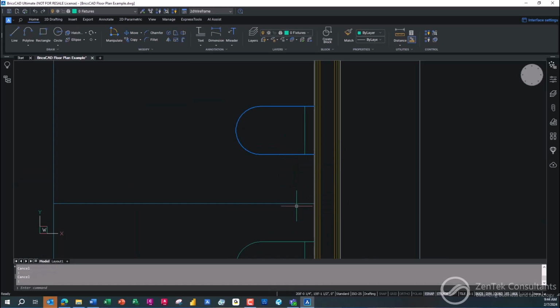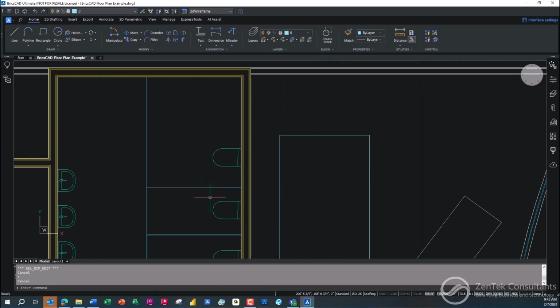I'll just click on the control, then here. Okay, that's 1 foot 1.5. Maybe that's not enough clearance. Now the key with this, the one that you pick on first, I'm going to pick the wall first, then I'm going to hold down the control and pick here. The one that you pick first will stay where it is. So instead of 1 foot 1.5, that's actually supposed to be 1 foot 4, 16 inches. All right, I'll just put in 16 inches, and you see, it moves the toilet up. I know that I'm laying things out accurately.